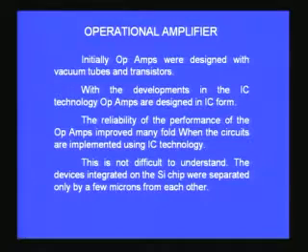Apart from this advantage of miniaturization and power supply and things like that, you also have several additional features when we go to operational amplifiers. One of the important features I would perhaps briefly mention is that the reliability of the performance of the op amps improves because you have made them in integrated circuit form. Why is it so? This is not difficult to understand. The devices are integrated on a silicon. I have shown you 20 transistors, 11 resistors and 1 capacitor, all integrated in a very small region of less than 1 millimeter by 1 millimeter square.